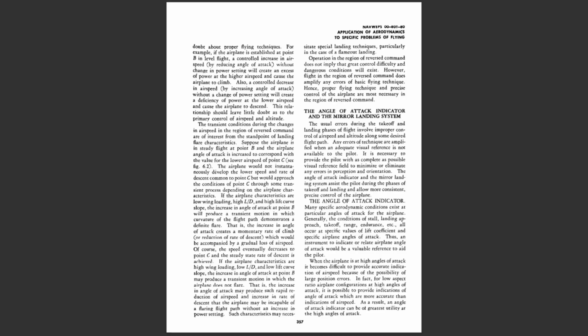Many specific aerodynamic conditions exist at particular angles of attack for the airplane. Generally, the conditions of stall, landing approach, takeoff, range, endurance, etc., all occur at specific values of lift coefficients and specific airplane angles of attack. Thus, an instrument to indicate or relate airplane angle of attack would be a valuable reference to aid the pilot.